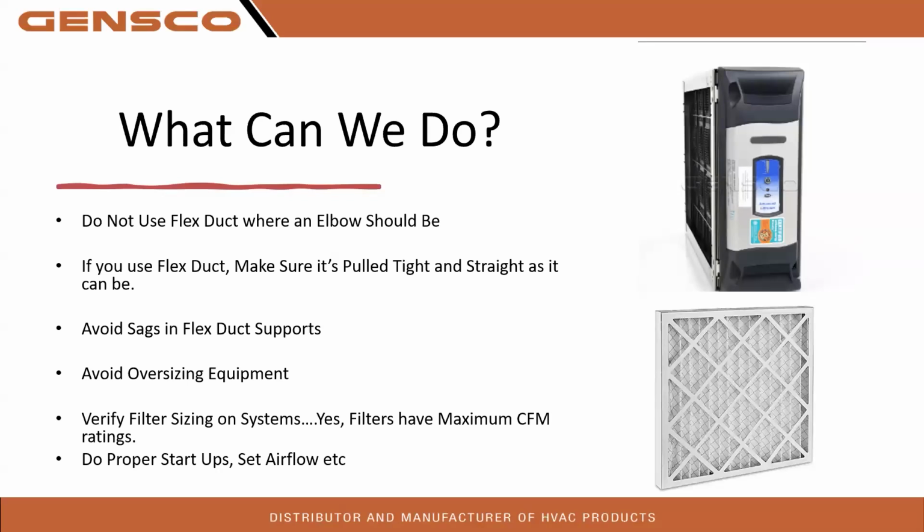If you take a home that's, let's say the home is 2,000 square foot, right? 2,000 square foot home. And let's say it averages 10-foot ceilings. That is 20,000 cubic feet of air in the home. So take a little box, a little cubic feet of air, and you put it in the home. There's 20,000 of them, right? And if it's a 2,000 square foot home and we've got a 3-ton unit moving 1,200 CFM, that means it's going to have 16 air changes an hour. That's a lot of air changes.